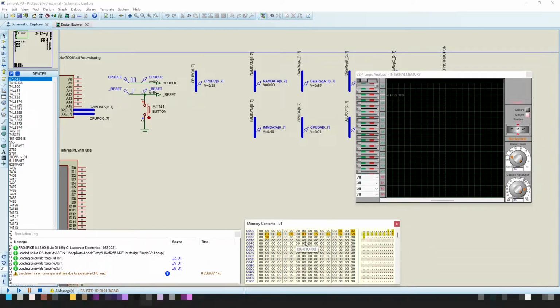And the memory window is showing what we expect to see in terms of program execution. So we're expecting to see 1, 2, 3, 5, 8, D, 15, 22, 37, 59, and 90 in hex, all separated by 0 values. These 0 values don't get written. And this is just showing us that we are writing a value, incrementing the address register by 2, writing the next value, incrementing it by 2, writing the next value, and we're doing it for the expected number of iterations in the loop. I think.